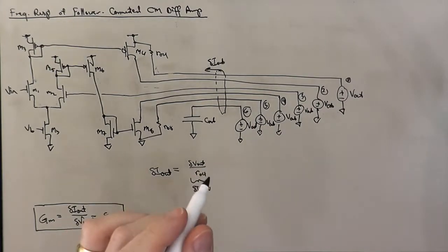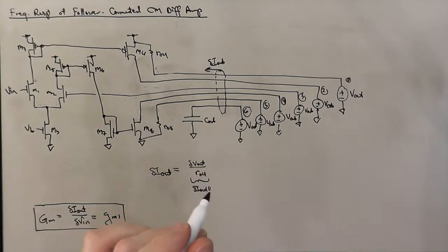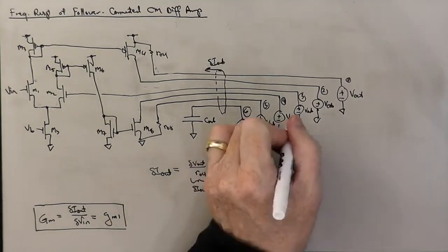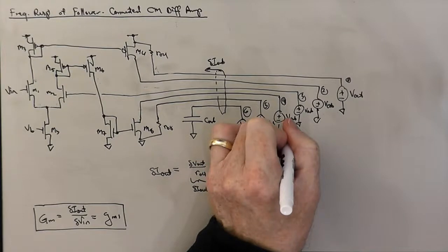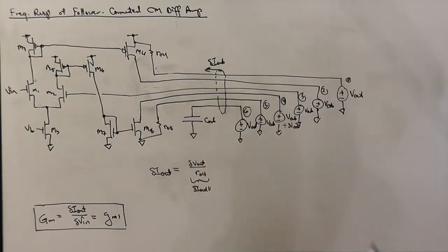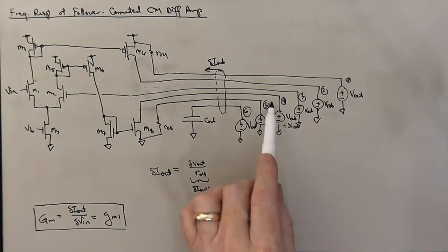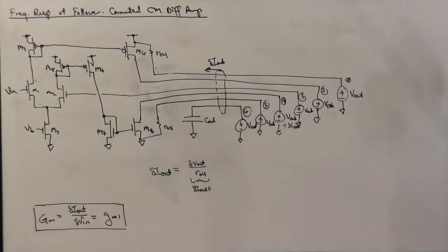All right, so let us skip over number 3 for the time being, and let's move on to branch 4. Well, branch 4, what's that connected to? That's the drain of M8. Well, again, that's the drain of an ideal transistor. In this case, it's an NMOS transistor that's operating in saturation.